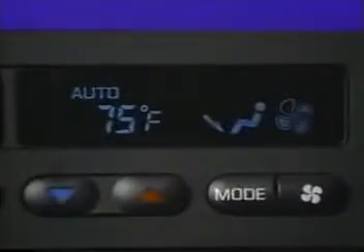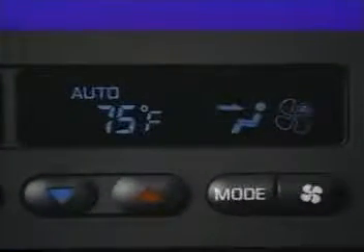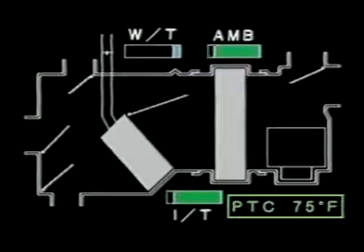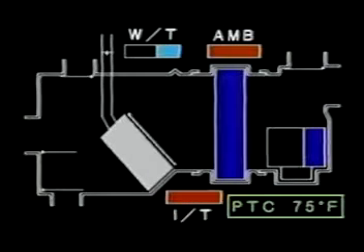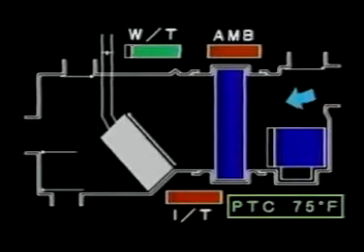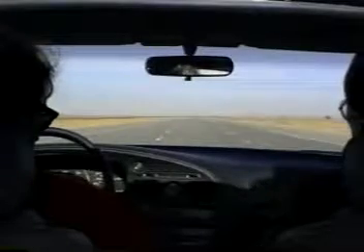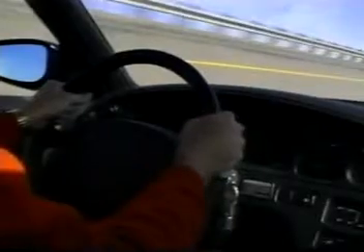The built-in microcomputer has an automatic amplifier that calculates how to produce a cooler in-vehicle temperature when the passenger feels hot. The automatic amplifier controls the air temperature, air volume, air inlet, and air outlet positions. Since the automatic amplifier in each sensor substitutes for a human ability to sense and to manually control temperature, the automatic air conditioner system can create an efficiently comfortable environment with simple operation. This video will explain the control function and basic operation of the automatic air conditioner system.